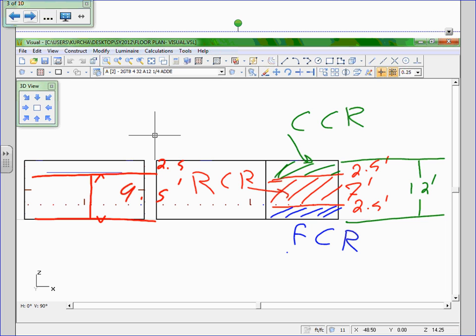And I'm going to ask you the following. What is the floor cavity ratio, just by looking at this? 0. What's the floor cavity ratio? 0. Absolutely. Why? Because the height of the cavity is 0. If you multiply 0 by anything, what do you get? 0. Just by looking at it. Now, if I ask you what's the room cavity ratio, no problem. You put 9 in the formula, multiply it. What's the height of the ceiling? Ceiling cavity ratio, floor cavity ratio.